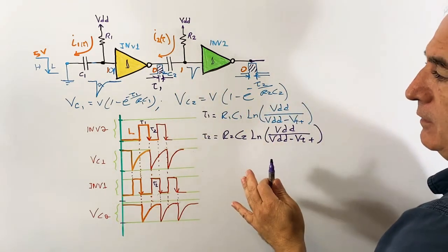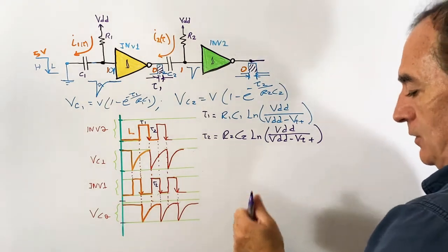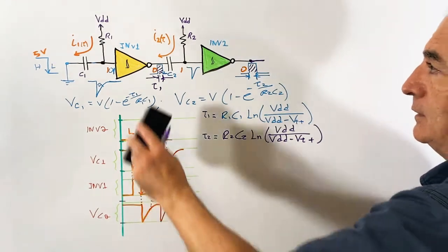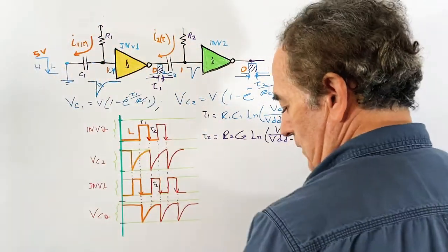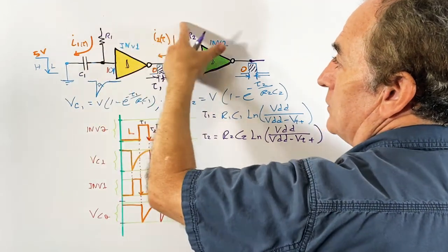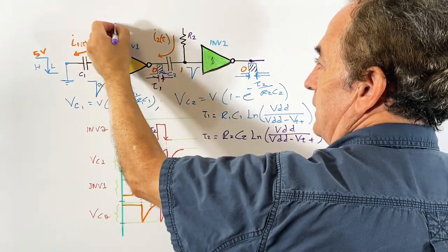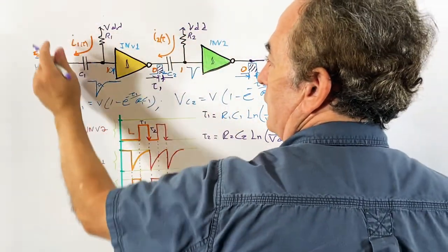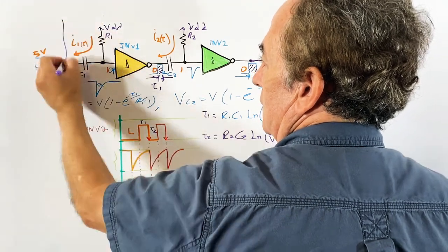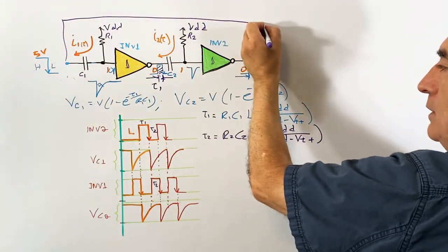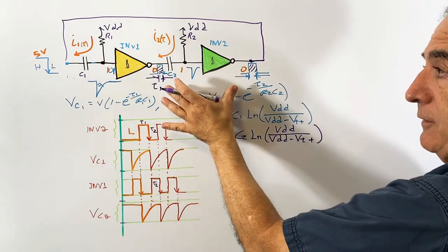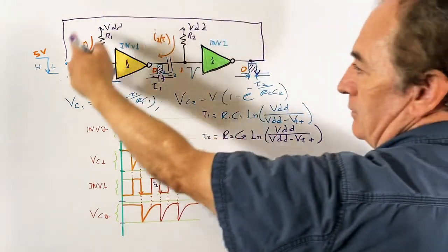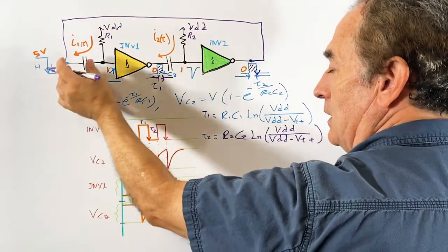So to make an oscillator from this circuit, I just need to make a feedback, and I'm just going to remove these levers. The power continues right there. Of course, this is VDD, this is VDD. So if I remove this and I make a feedback loop, this becomes an oscillator, because when this pulse ends, it'll trigger the first edge detector.